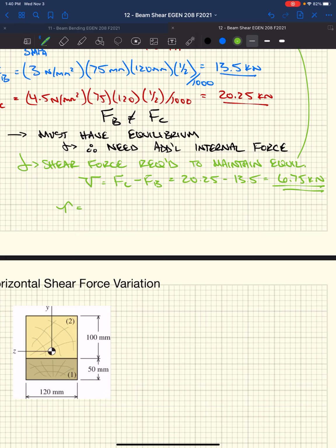All right. So we have a shear force. Well, we know from earlier chapters in the text we have shear stress. Shear stress is, again, force over area. In this case, we use our shear force as the force, and then the area over which it acts. So we have V over A, and we can figure out the shear force, right? 6,750 newtons, same as 6.75 kilonewtons.